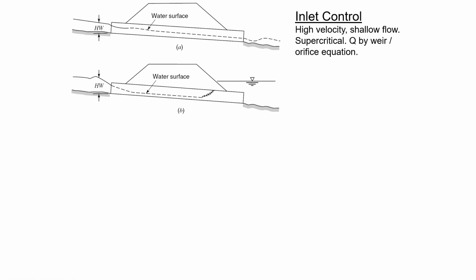You maybe remember the orifice equation, which says if you've got like a tank of water and a hole in the tank, then the rate that the water is coming out is related to Q equals A square root of 2GH, where H is the height of the water from the water surface down to the center line of the orifice.